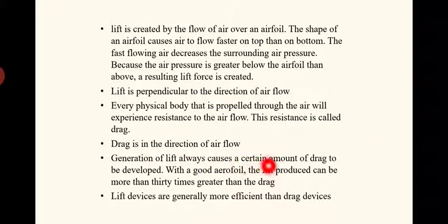Generation of lift always causes a certain amount of drag to be developed. Always along with lift, there will be drag also, but the lift force will be much higher compared to the drag force in the case of aerofoil shapes. With a good aerofoil, the lift produced can be more than 30 times greater than the drag. See that difference? The lift force produced by the aerofoil shape will be around 30 times more than that of the drag force. So that means high energy is able to be generated with that aerofoil shape, and of course, that much energy we can harvest. So lift devices are more efficient than the drag devices.